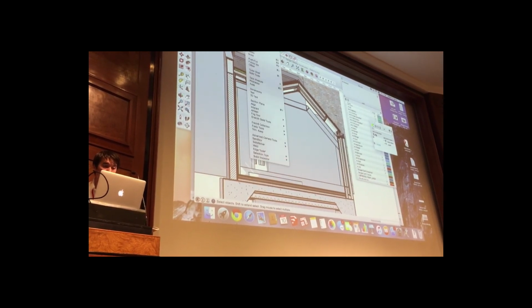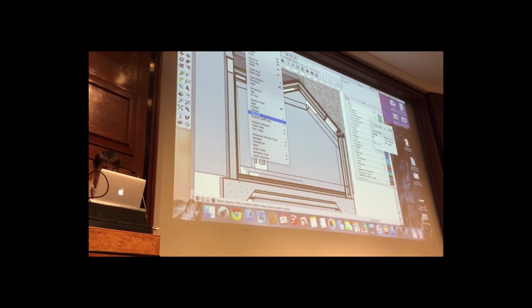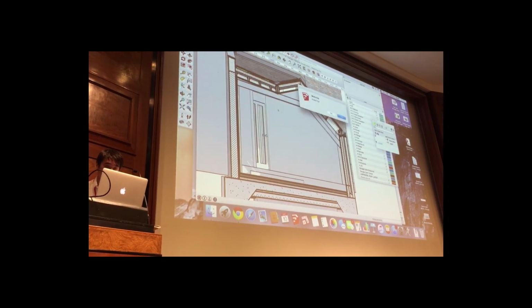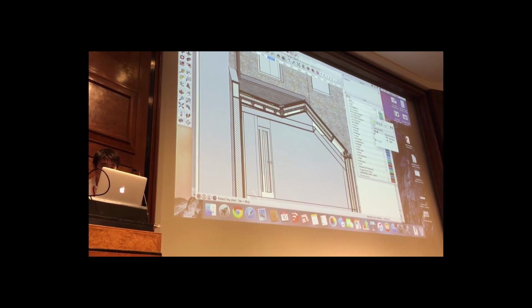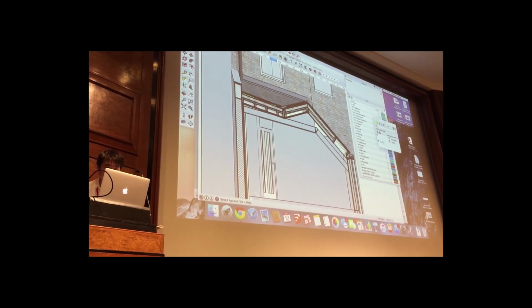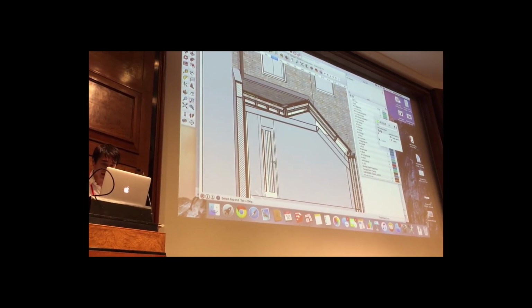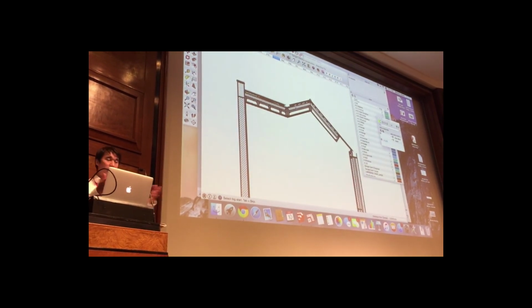And I use Eneroth's fog tool to click on the section face, and then I type in a distance like 100 mil, and then it hides everything behind.